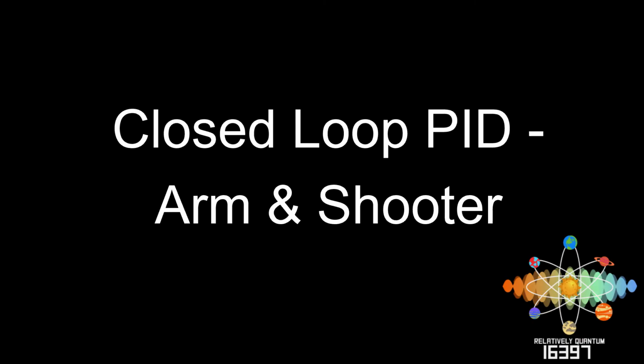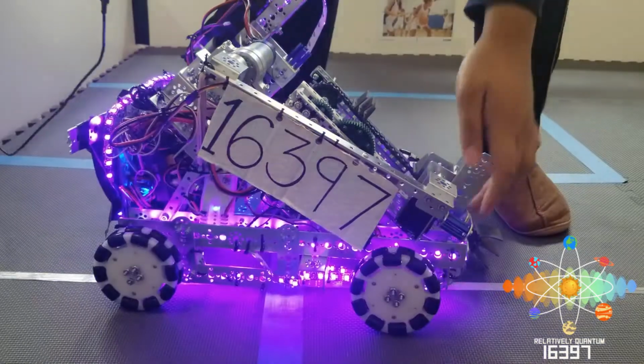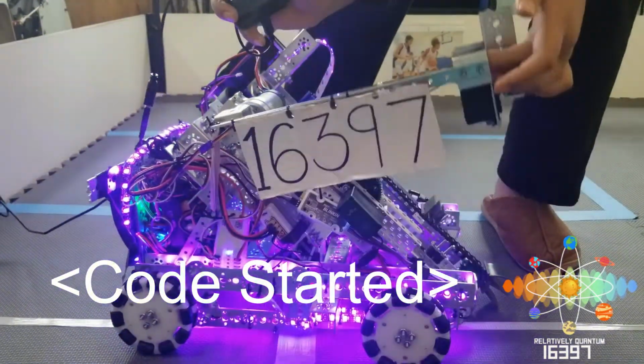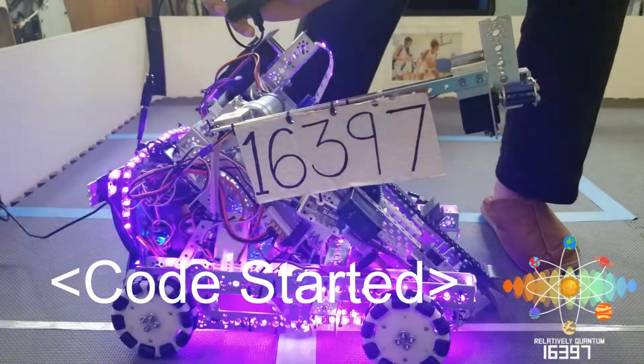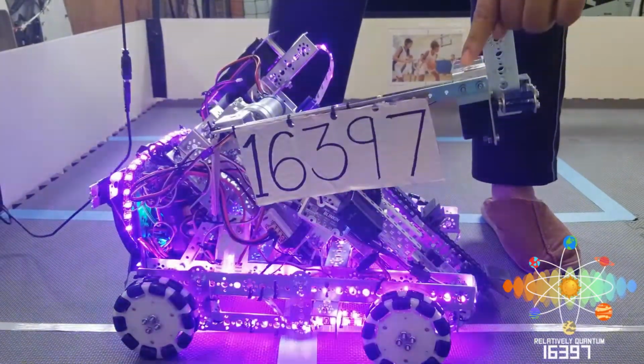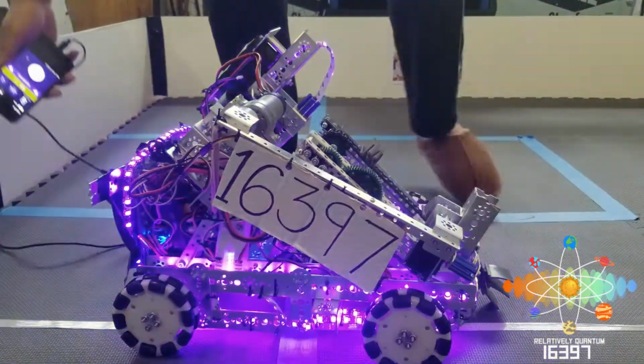Controlling the robot drivetrain is important, but so is controlling our arm and shooter. To effectively control them, we used a closed-loop PID system, which is imperative for their function. Starting with our arm, the encoder values are tracked in a simple controller where if the arm goes past the encoder position, then negative power is applied, or if it falls behind, positive power is applied. In this way, we're able to hold the arm in positions where it's not able to mechanically hold itself.